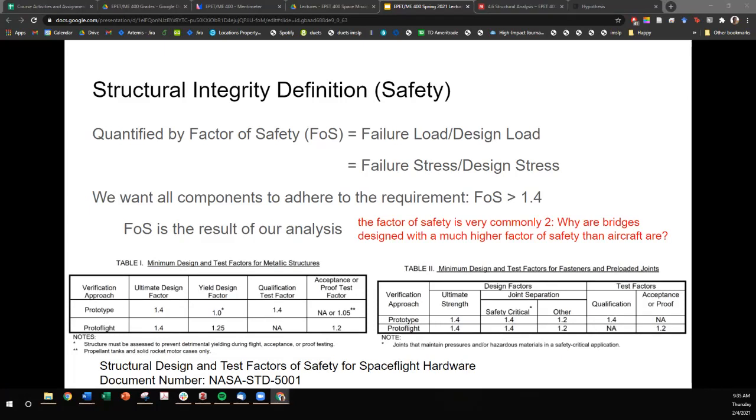So the explanation for that question is, buildings commonly use a factor of safety of 2 for each structural member. The value for buildings is relatively low because the loads are well understood and most structures are redundant. Pressure vessels use 3.5 to 4, automobiles use 3, aircraft and spacecraft use 1.2 to 3, depending on the application of materials.